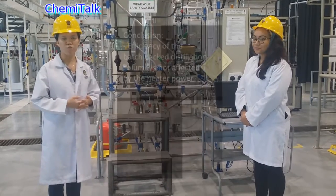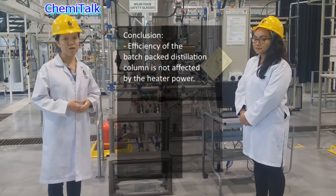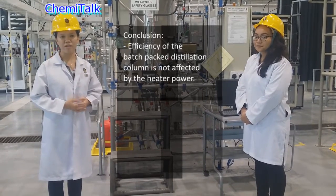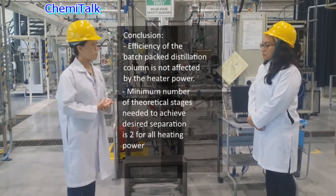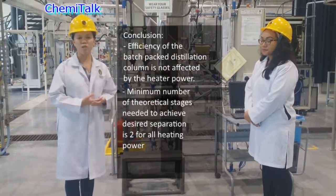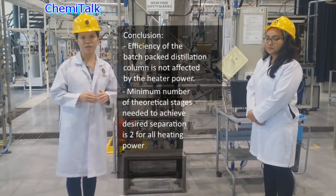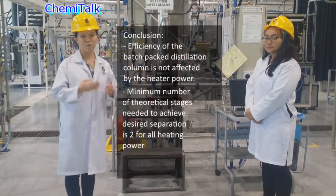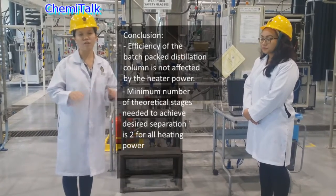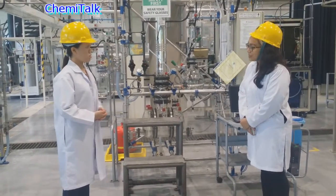Therefore, we can conclude that the efficiency of the batch pack distillation column is not affected by the HETP. Thus, in this experiment, which is in the total reflux conditions, the minimum number of theoretical plates that is needed to carry out the desired separation is 2 for all the heating power. So how will the changing of the heater power affect the experiment?